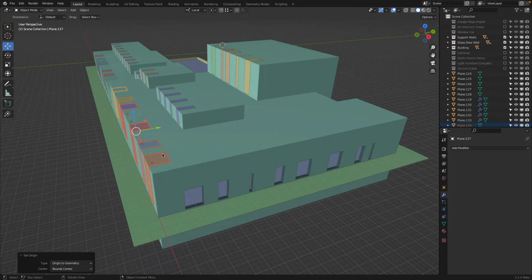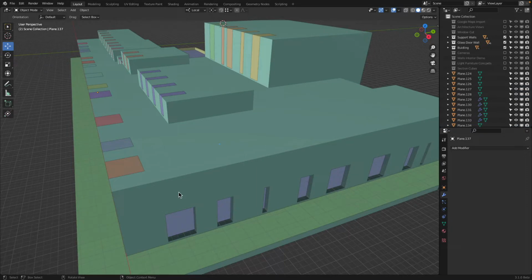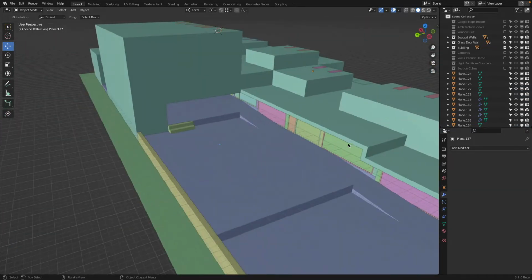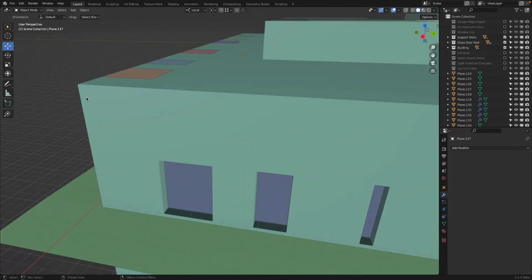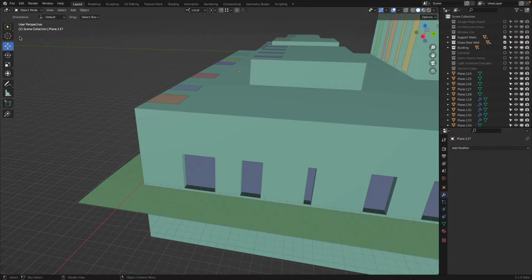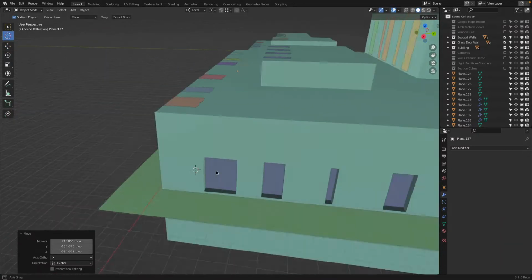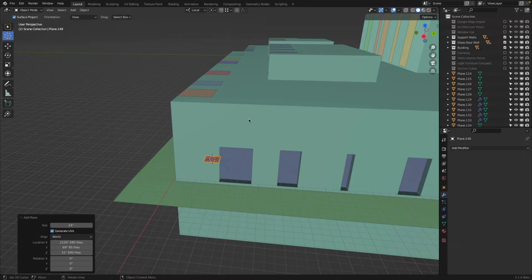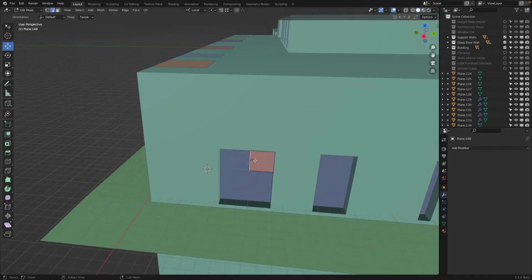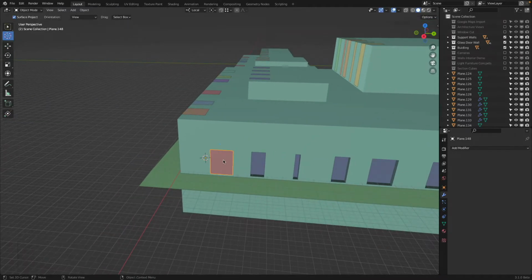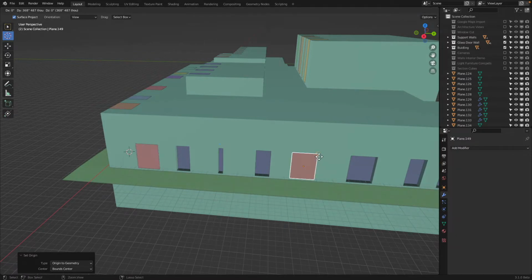So we ignored building the window frame. Now we could do this. We learned how to do this here with there, but we will skip this step. So here, how do we do this? The 3D cursor, we can drag onto here, Shift A, plane. Then we will go into edit mode, R, Y, and 90. G, and you see how I'm snapping this down. There we are. Tab. In object mode, right click, and then Shift D.